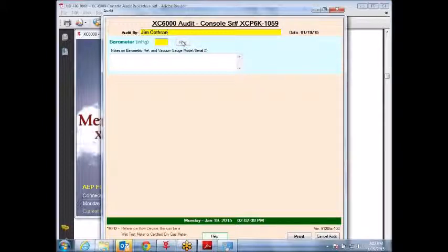Normally, if you read the manual, it talks about hooking this up and warming it up for about 30 minutes, 15 to 30 minutes, by connecting the reference meter to it and just pulling air through it. For sake of time, I'm not going to do that today, but basically just connect it and set up a 30-minute constant 500 cc test and just let it run.